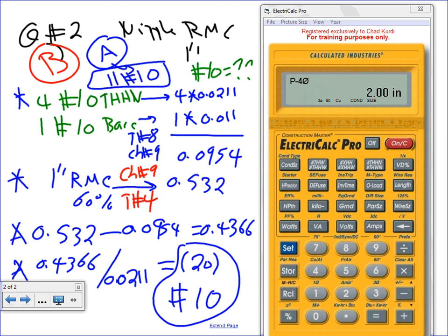Nick, do you want me to go over it? Once we got it 1 inch on the C, right? Yep. Then we have to go under the 60 percent column? Yep, because it's a nipple. A nipple is 24 inches or less. Remember we said, guys, 24 inches or less gets special treatment. Any question, guys, about this? Everybody got the answer for A and B?